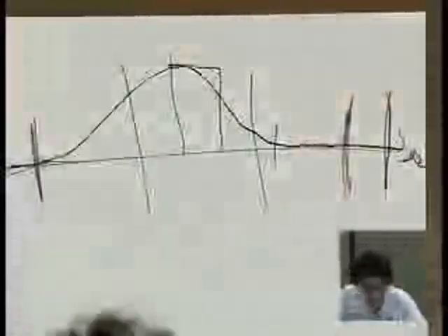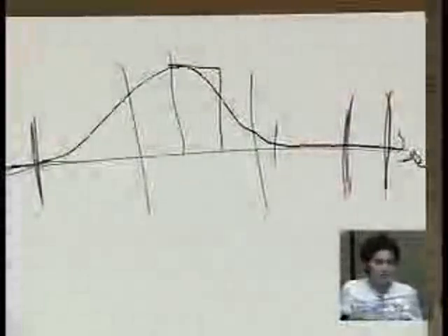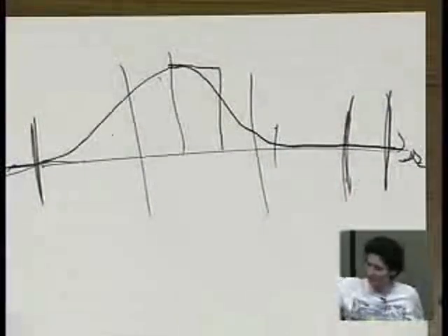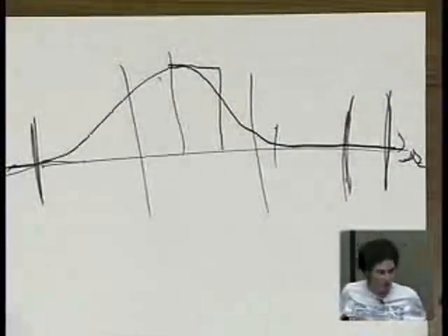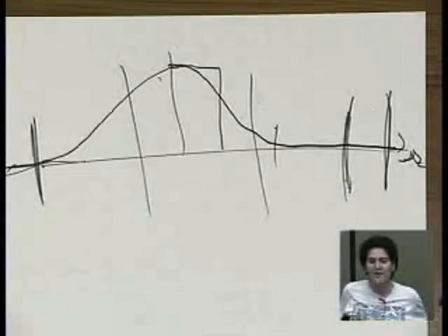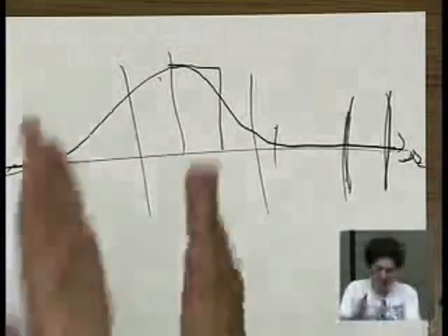As an example, on your cell phones, the effective bandwidth you're getting out of your voice is not even 3 kilohertz. It's more like 2 kilohertz. When the channel becomes bad, the sampling goes down, and that's why you have so much distortion, right? So the bottom line is you can make any signal any band limitedness that you want, as long as before you start sampling it, you band limit it.